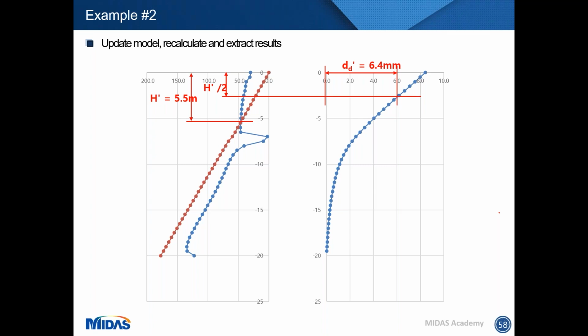You have mentioned in example 1 the use of model subgrade reaction. Are the springs produced infinitely elastic? How do you ensure compatibility between stress and deformation? Well, they are infinitely elastic. I understand that there is no yield value. I'm not sure if I'm interpreting the question right, but yes, they are completely elastic because that's how the method of subgrade reaction works.